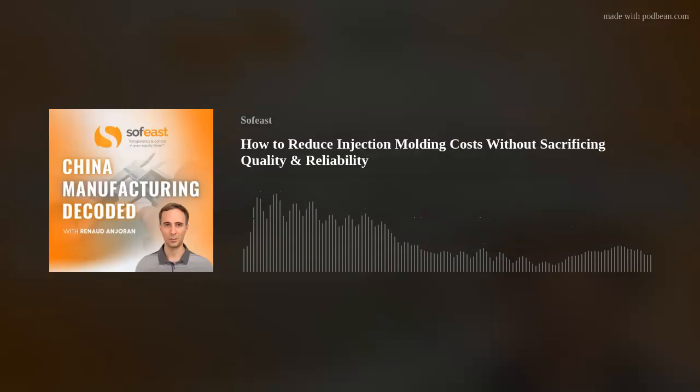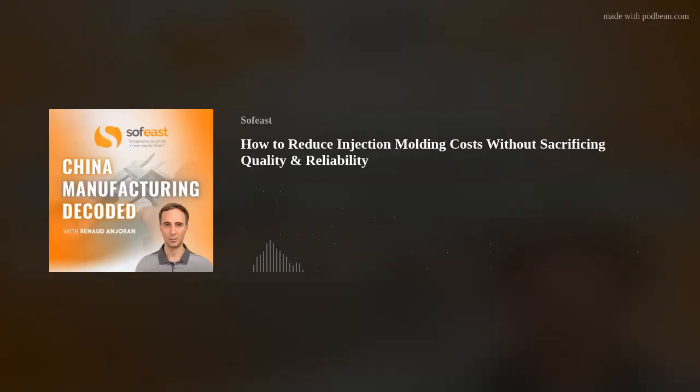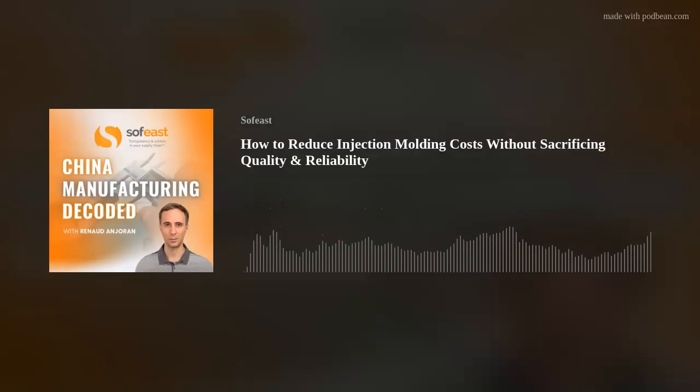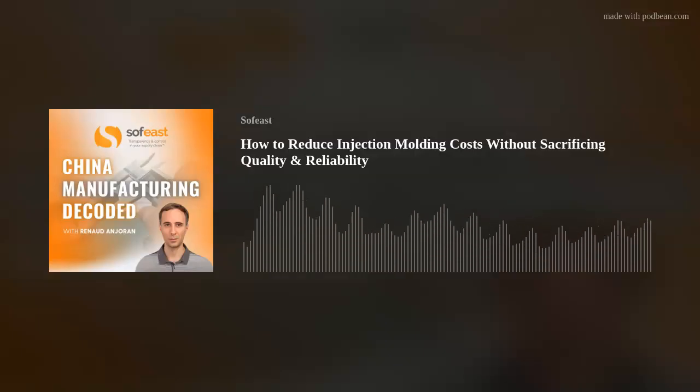But this is what you call a family mold, because you've got so many different parts in one mold shot itself. It worked because all of the components are really, really small. Now, if you've got a total imbalance, so you've got one larger part and then a number of different small parts in there, it can be a little bit tricky to balance the yield all of the time.